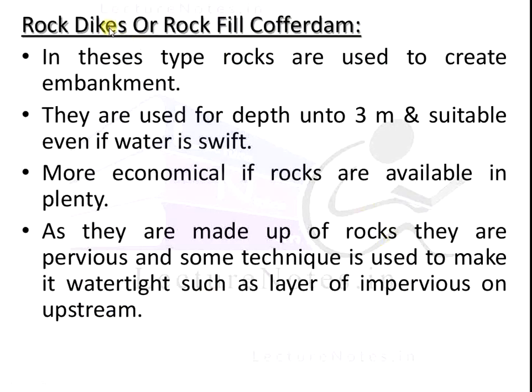Next is the rock dike, or rock-filled coffer dam. In this type, rocks are used to create the embankment. They are usually used for depths of up to 3 meters and are suitable even if the water is swift.